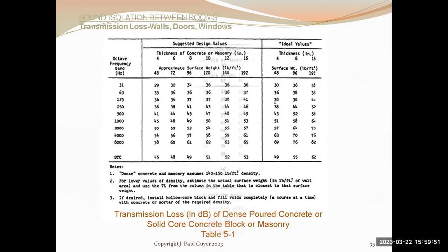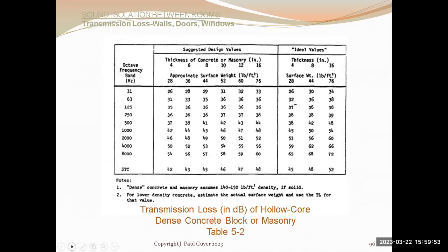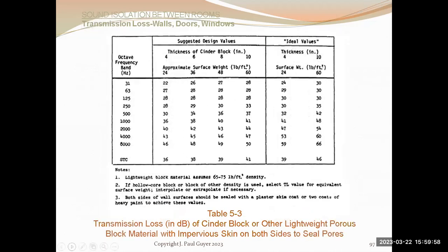And here is more of the same. So all building materials, essentially, you can represent by a table like this that relates the design parameters: 4 inches thick, 6 inches thick, 8 inches thick, to the sound reducing characteristics at the different frequencies.